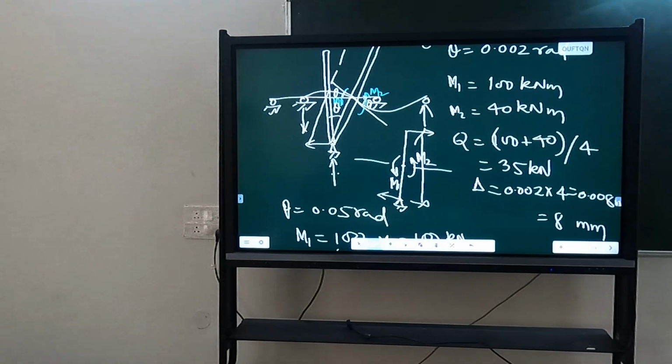So ductility ratio is theta u by theta y. Suppose ductility ratio for one beam is larger, but its theta y is also smaller. So what will happen to theta u? Theta u in both the cases is same actually. So if you calculate delta u, it will come out to be the same for both the beams. So you calculate for any beam, doesn't matter. Answer will be same.